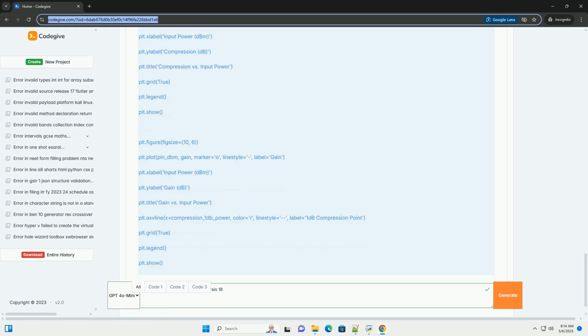6. Self-biasing. Examine the DC bias voltages and currents in your circuit as the input power changes. If the bias is shifting significantly, this could be affecting the gain and linearity. You might need to add bias stabilization circuitry. 7. Frequency dependence. Perform the power scaling analysis at multiple frequencies to see if the behavior changes.